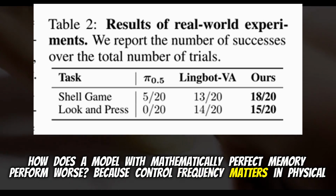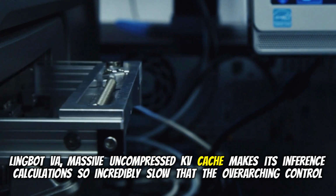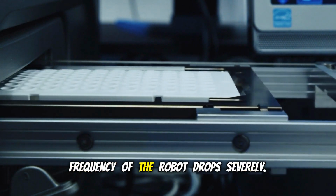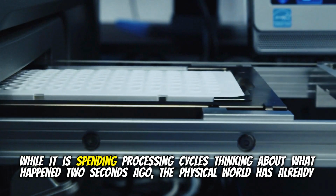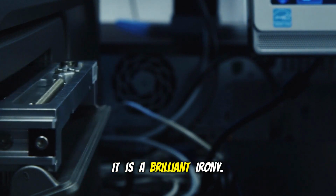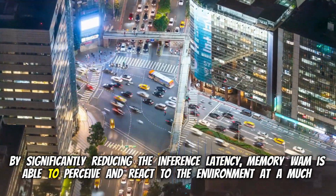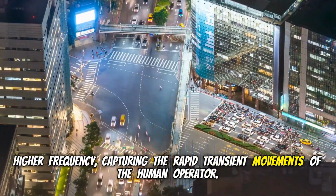Because control frequency matters in physical robotics. Lingbot VA's massive uncompressed KV cache makes its inference calculations so incredibly slow that the overarching control frequency of the robot drops severely. Right. It takes so long to process the past that it literally misses the camera frames where the human swaps the cups. Wow. While it is spending processing cycles thinking about what happened 2 seconds ago, the physical world has already changed in front of it. It remembers too much to react in time. It is a brilliant irony. It really is. By significantly reducing the inference latency, MemoryWAM is able to perceive and react to the environment at a much higher frequency, capturing the rapid transient movements of the human operator.